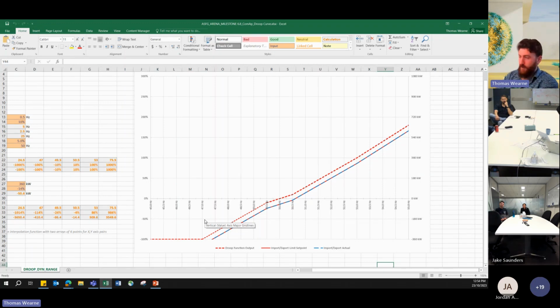Yeah, no, that's a hugely good point. We haven't disabled the protection settings in inverters. So while my graph here might show things happening at 54 Hertz, the inverter disconnected way before that. And it's fine that happened. The curve is there to illustrate a point, and hopefully the frequency doesn't change by as much as it would have otherwise if you hadn't provided the response.